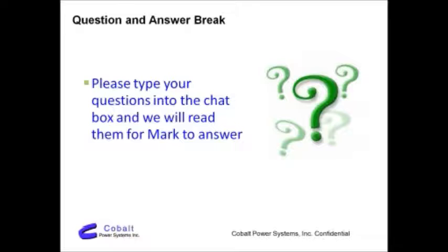Great answer. Okay, back to batteries here. Are there other battery types with longer lifespan? There are. That's a great question. The two major categories of batteries are sealed lead acid, which is what we talked about before, and flooded batteries. Flooded batteries are designed specifically for solar, and flooded means that you have to maintain them. You have to check the electrolyte level. You have to get out your hydrometer and check the specific gravity. You can only put in distilled water. You have to equalize them every month or two, which is a strong charging cycle to stir up the electrolyte.